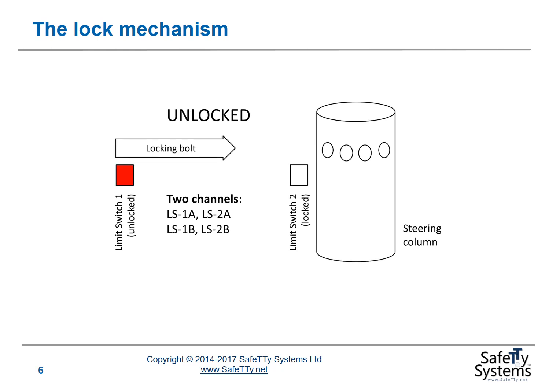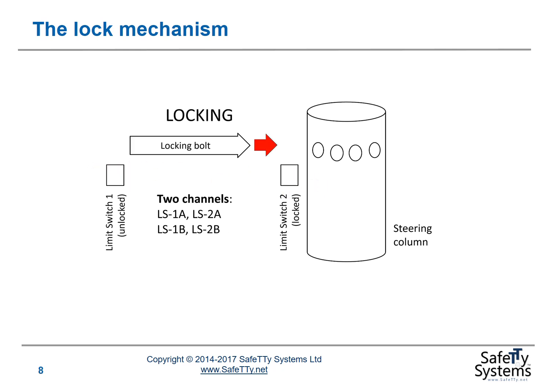Limit switch 1A and 1B are both set when the system is fully unlocked. There's a situation when we're unlocking when neither switch is set. So neither switch is depressed during the unlocking operation. Similarly, during the locking operation, there's an interval when neither switch will be set.